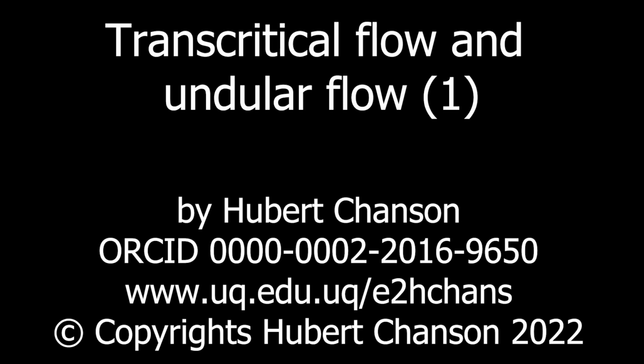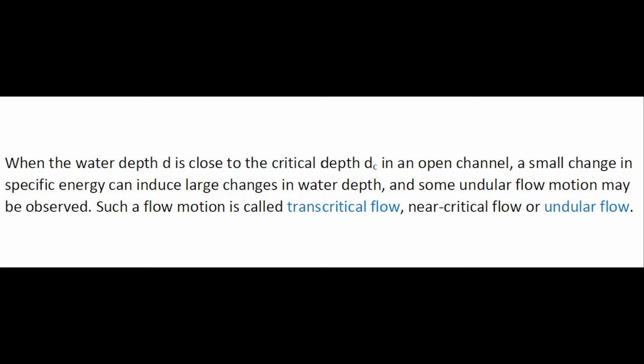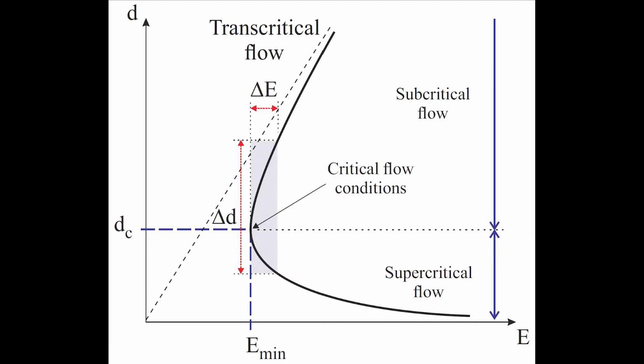When the water depth is close to the critical depth in an open channel, a small change in specific energy can induce large changes in water depth, and some undular flow motion may be observed. Such a motion is called transcritical flow, near-critical flow, or undular flow. This is illustrated in the relationship between specific energy and water depth.